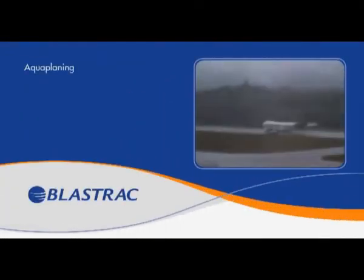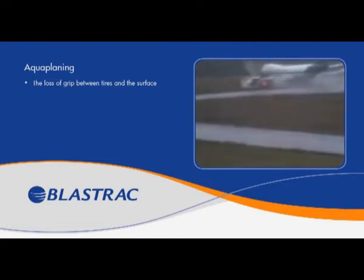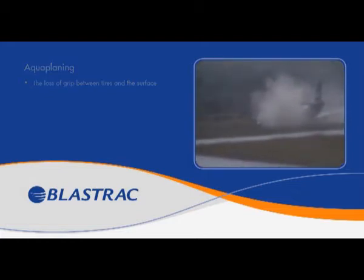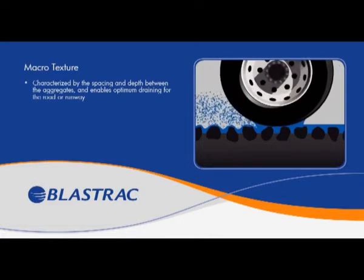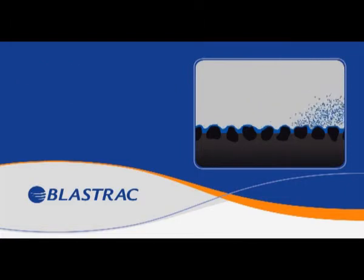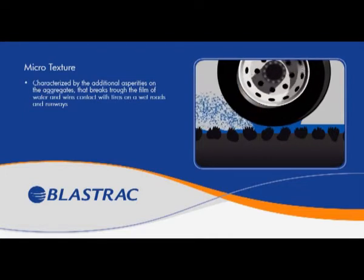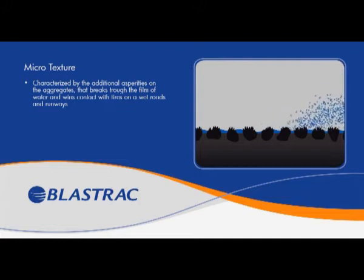The danger on roads and runways during heavy rain is the loss of grip between tires and the surface. When the road or runway is new, it has two characteristics, providing a good grip for tires. Macro texture, which is characterized by the spacing and depth between the aggregates and enables optimum draining for the road or runway. Micro texture, which is characterized by the additional asperities on the aggregates that break through the film of water and win contact with tires on wet roads and runways.